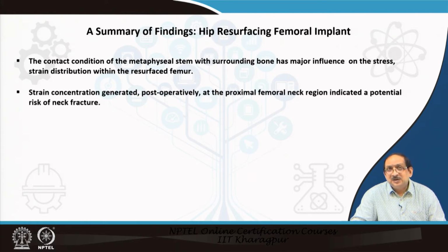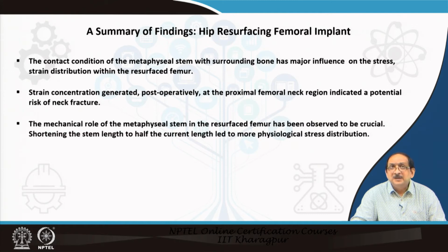The strain concentration generated postoperatively at the proximal femoral neck region indicated a potential risk of neck fracture within a few months after surgery. The mechanical role of the metaphyseal stem in the resurfaced femur has been observed to be crucial. Shortening the stem length to half the current length led to a more physiological stress distribution.